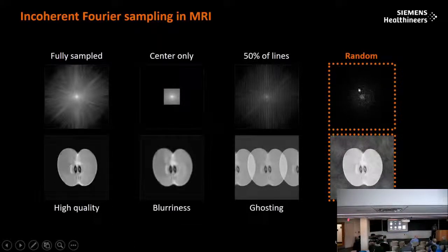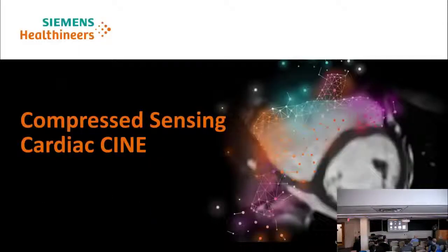So instead, we do variable density sampling where we sample more densely in the low frequencies. That's kind of intuitive because if you have some a priori idea of where your signal is, you want to sample more where your signal is. And so these are the kind of images that we get just with a simple inverse Fourier transform, where there is a little bit of blurring, but that might not be visible because it's hidden under the noise. And the noise is not quite white, so it would be exactly white for a particular distribution of the sampling density, but it's reasonably close to white.